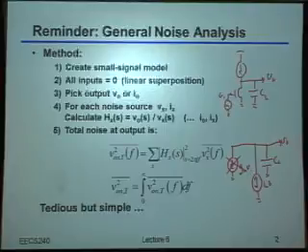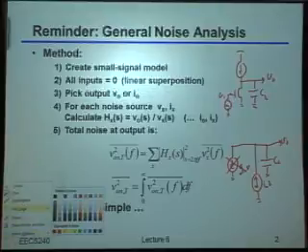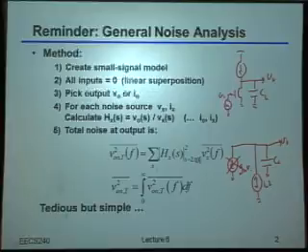And then once I have that, I can essentially integrate it and just add each of those sources together, right? So that's, again, really all that this expression here is saying. I just take each possible noise source, so that's why I'm iterating over this x. I figure out what its transfer function is, and I multiply the transfer function by the noise, either current or voltage density. And then at the end, if you want the total noise, you just look at this integrated value. Okay? So conceptually, this is really, really simple.